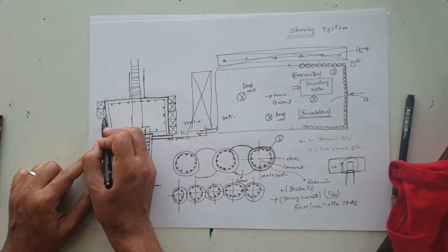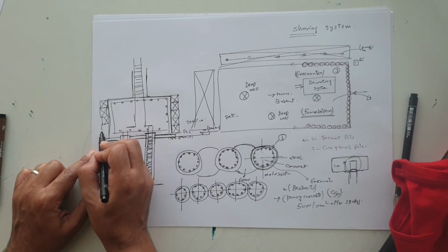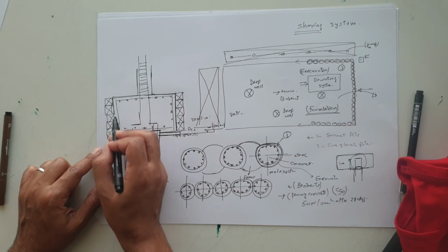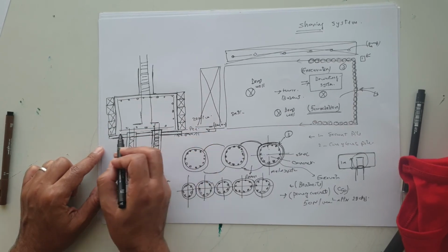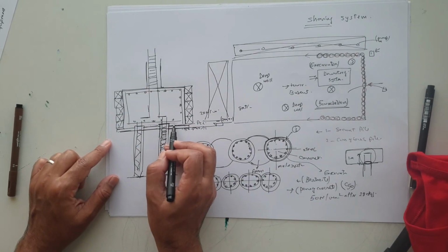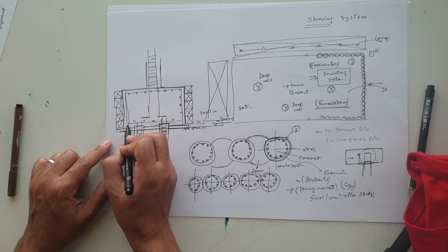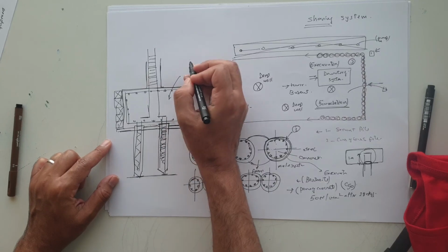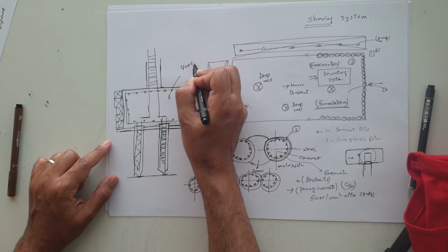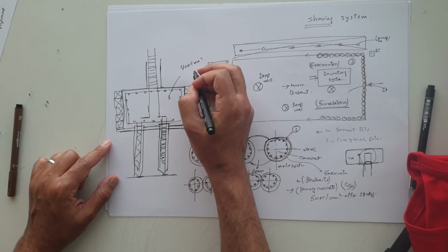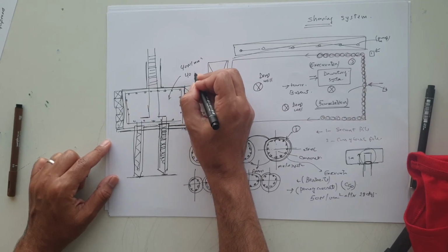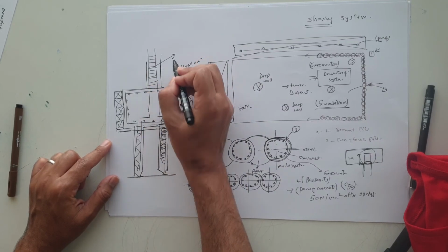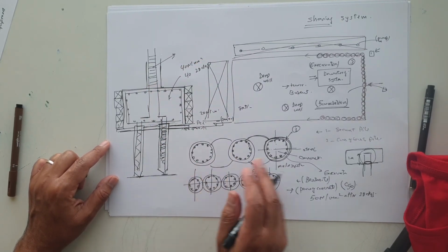After we finish all the block work around the pile and finish the waterproofing from inside, and put screed here to protect the waterproofing, we fix all the steel inside the pile cap and pour the concrete which is 40 Newton per millimeter square. The strength of the concrete is 40 after 28 days. This is the pile system.